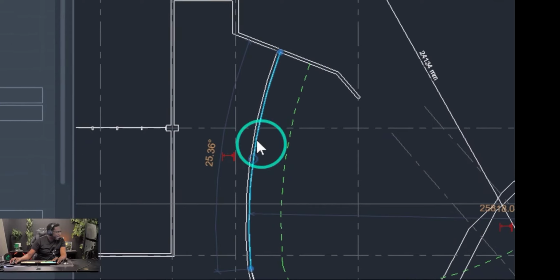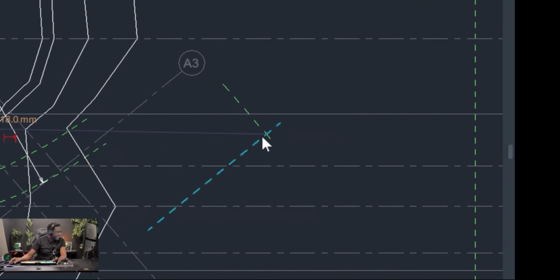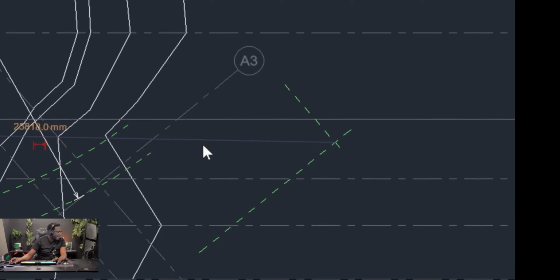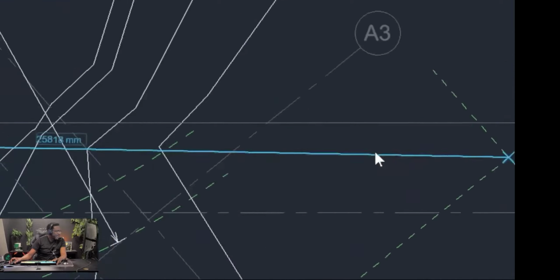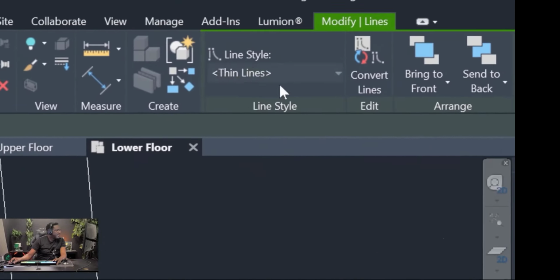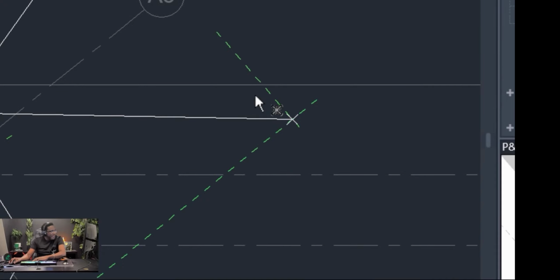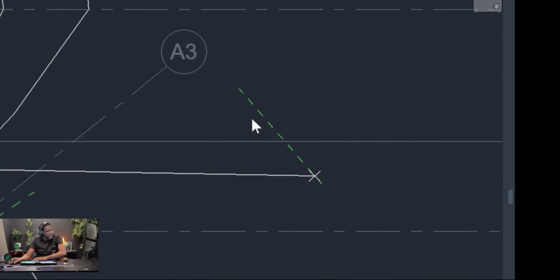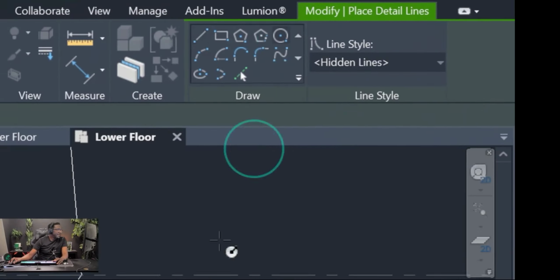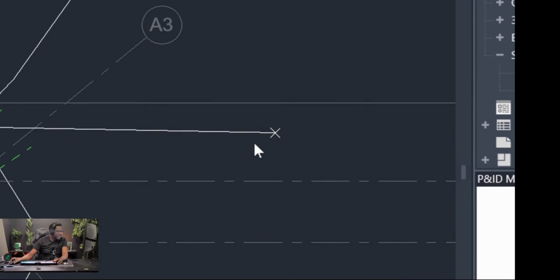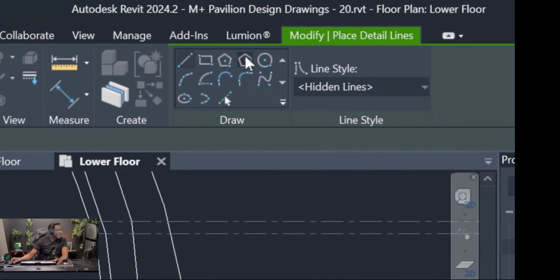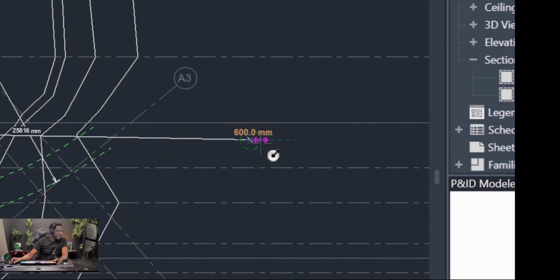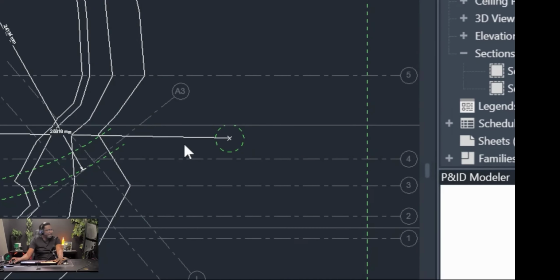That's to this point. Then also I want to do the same thing for this point, which endpoint is right here, which luckily we had already marked, because that's what we use to construct this curve. So in case you don't have, imagine that you had already deleted these lines. You wouldn't have had those lines there. So I'm going to put a circle there. The reason I put a circle there is that it's easy to snap to. And I'm just using a detail line because I intend to delete it when I'm done. I'm just putting it there.